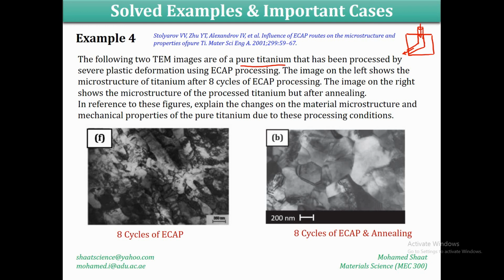Upon this process, we are achieving severe plastic deformation over the material, and this would result in a reduction in the grain size. And at the end, after 2, 3, 5, or even 8 cycles, we are going to end up with an ultrafine grain material, where the grain size will be severely decreased to approach hundreds of nanometers. Like we can decrease the grain size up to 300 nanometers, 200 nanometers in some cases, if we decided to use ECAP as one of the severe plastic deformation processes.